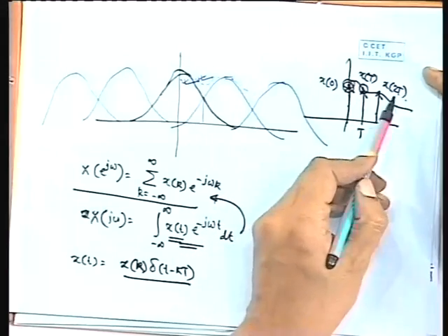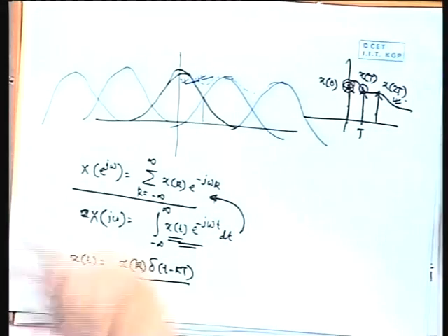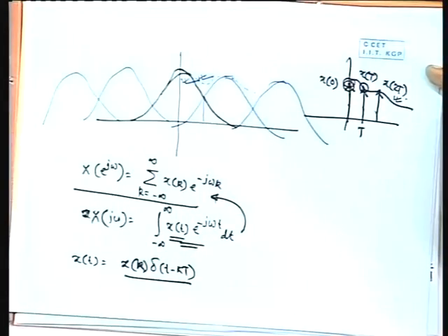Okay. Now this is all very fine, there is no problem, excepting that there is a big problem. What is the problem? The main problem is that the energy of the signal has been multiplied many times through this process. What is the energy of the impulse signal? That is the area under the curve. The area under the curve of the impulse train and the area under the curve of the original signal are roughly related by T. That is the continuous signal, that is integral x, simply because